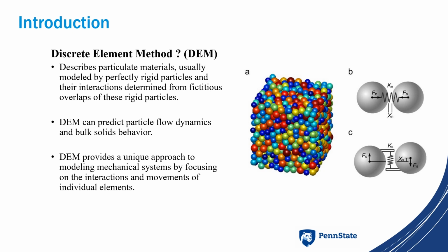And the advantage over the traditional method is that traditional continuum-based calculation techniques such as the finite element method or finite difference methods cannot directly reflect the discrete nature of these materials and structures. DEM fills this gap by allowing engineers to model and analyze the behavior of each element in the system, offering insights into phenomena that would be difficult or impossible to study otherwise.